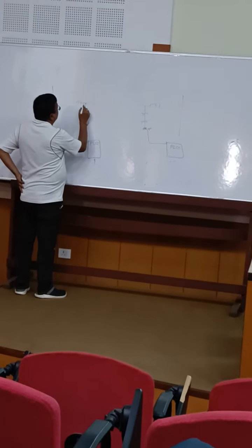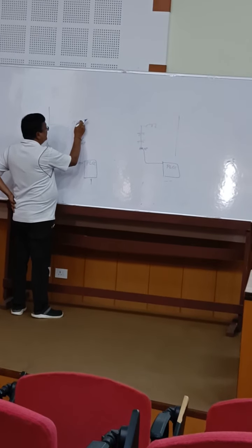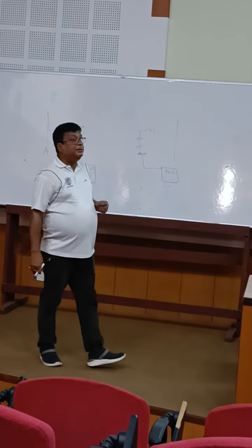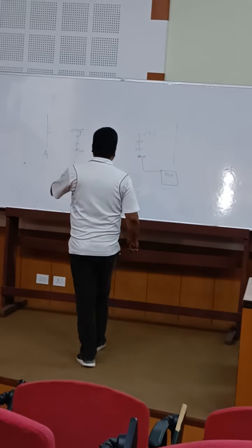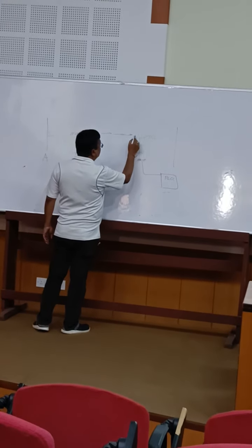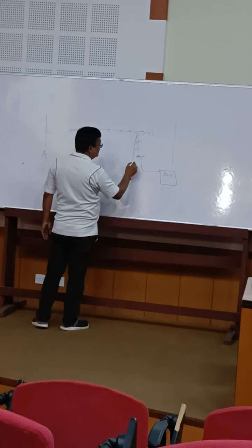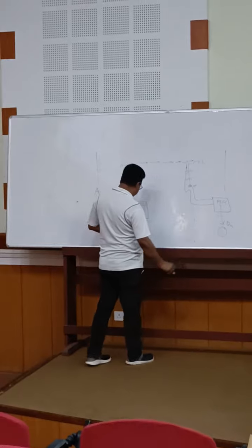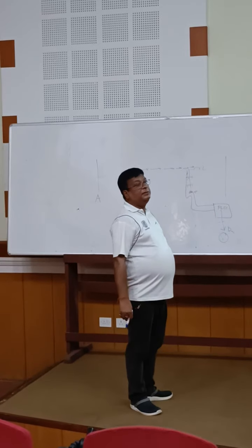So here the high frequency signal has two paths. One is this side, but if it starts traveling this side, the wave trap will stop it, because for high frequency the wave trap is a very high impedance. So naturally it will follow here. The high frequency signal will transfer like this. And once again when it lands here, you will have two options, one low impedance path, one high impedance. Automatically it will follow the low impedance path. Here demodulation will be there, and the person over here will listen to whatever is said. This is the reason why the CVT is before.